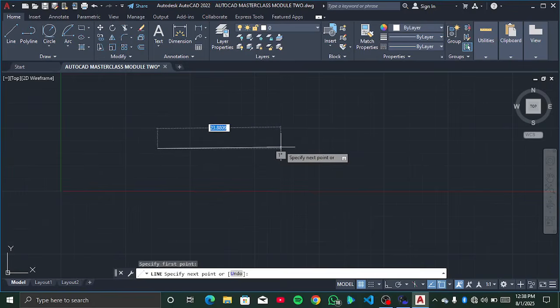Now, once you have AutoCAD, you can put in a definite value. The fact that the value inside there is highlighted with blue means that I can change it. For example, if I wanted a 30 millimeter line, I'll just type 30 and press enter. But if I want it to be a straight line, I'll leave my angle at 0, as you can see. I press enter. See it's 30, it has stopped.